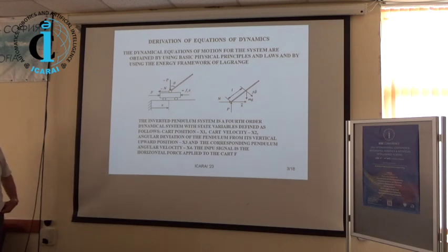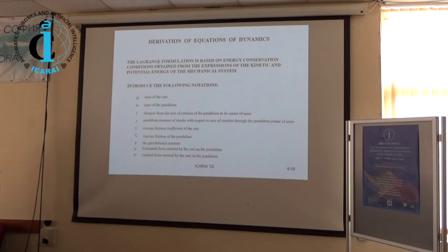So the inverted pendulum system is a fourth order dynamical system, and as I mentioned, we have the position of the cart, the angular position of the pendulum, the velocity of the cart, and the angular velocity of the pendulum.